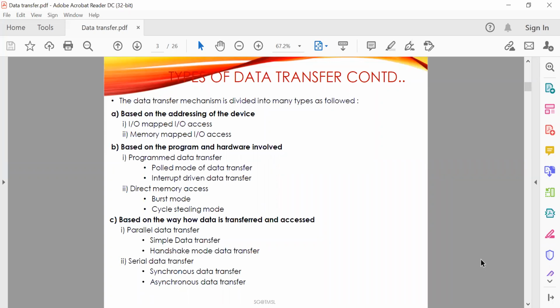that is called the hold state. Okay, so DMA performs high speed data transfer to and from mass storage peripheral devices such as hard disk drives, magnetic tapes, CD-ROMs, and video controllers. So everything. Okay, so hard disks may have a transfer rate of 5 Mbps, that is 1 byte every 200 nanoseconds. Okay, so performing such data transfer using the CPU is not only undesirable but also unnecessary, since the CPU transfer rate is limited by the speed of the memory and the peripheral devices.